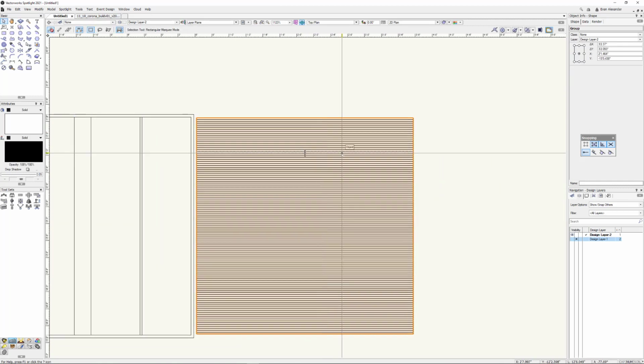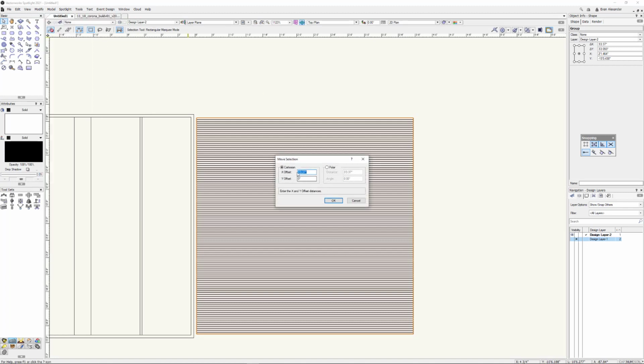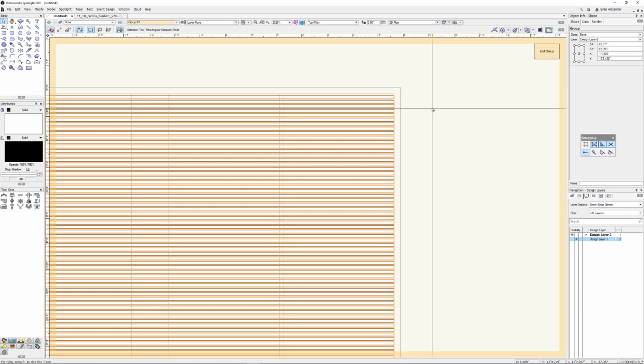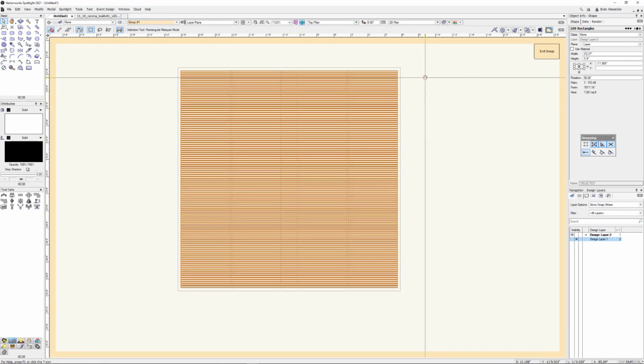All right, so I can't extrude a group because it's a group. So first, let's move it back into position. Let's say modify, move. And I'm going to just put a subtraction on there and slide this guy over. And then let's go into the group here. Now, this is made up of 109 pieces, but if we now say Control E, extrude, we can extrude all 109 of those, and it's only going to be one object, one extrude. So I'm going to extrude this 1/4 inch.